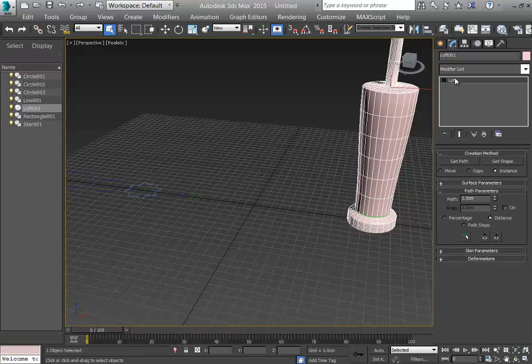So nice. Now, actually, I hit the 2, but it opens something else. Okay, means I need to change the styles from the loft modify section. Here, for example, accidentally something gone wrong and it hasn't been finished yet. So what you need to do in that case, you need to select your loft tool, you need to go to modify section, and here your setups are still staying.